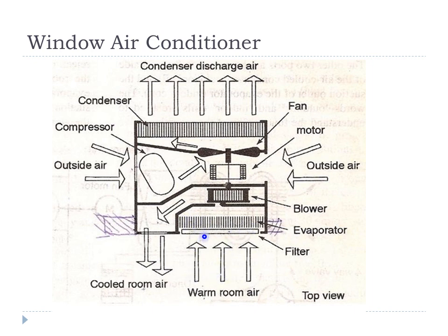When the warm room air comes into contact with the evaporator coils, it gets cooled, and an excess amount of humidity, that is moisture, also settles in the form of fine droplets, so it becomes liquid water, and the air gets cooled and channelized, you can see here, and from this channel it comes back into the room, so you will get cooled room air here. So this is how warm room air was converted into cooled room air in this compartment.